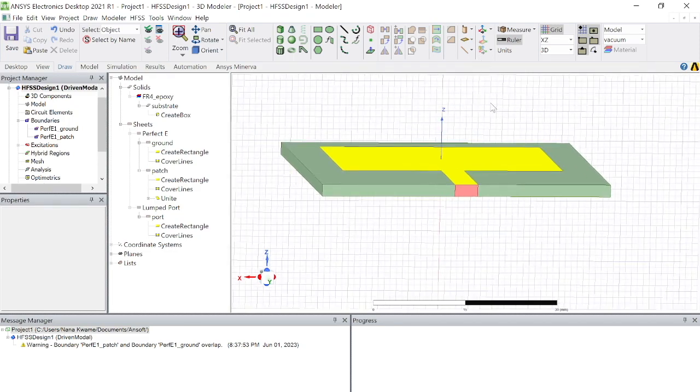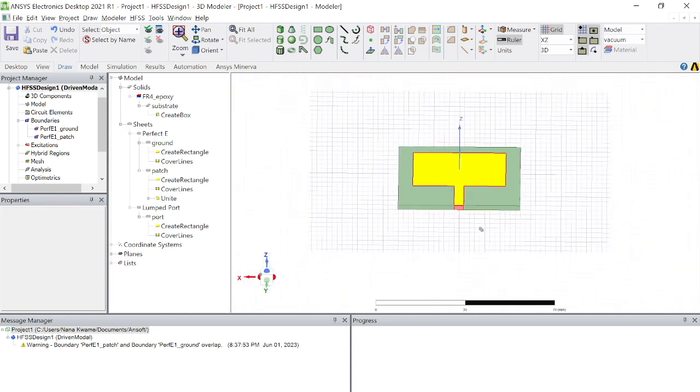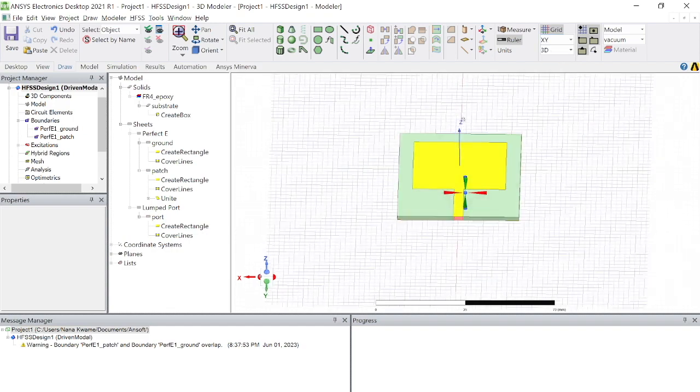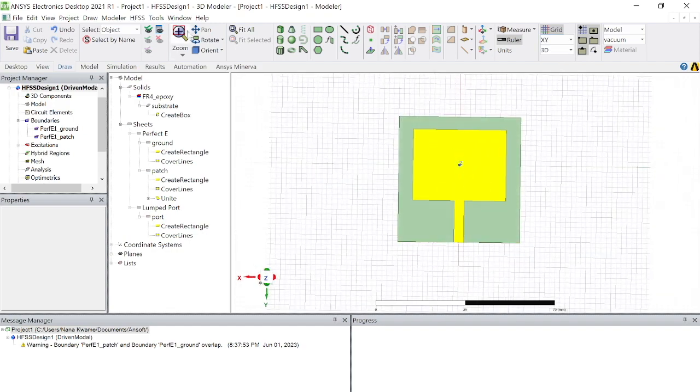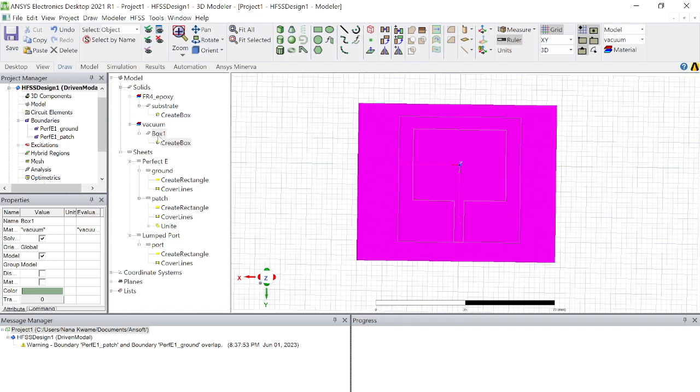I'm left with a radiation box. I'll change the plane to SZ so that I can work in it perfectly. To the radiation box. Usually it is assigned that the distance from the antenna to the box on each side will be lambda by 2, but maybe how it is assigned will be okay. So now I'm having a box. I'll call it radiation box, rad box.